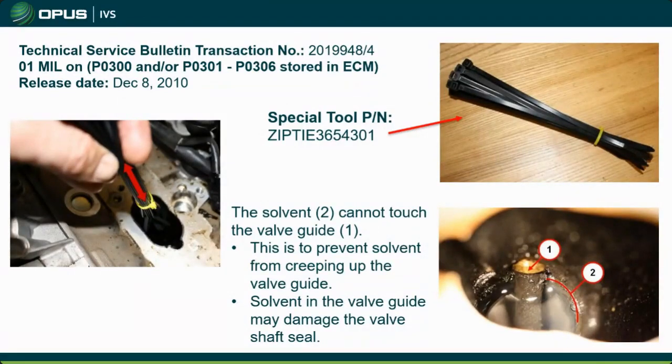The short trip driving is just a killer on these direct injection turbo and supercharged systems, because they never get up to operating temperature. The breather system never really gets cooking, in the sense that you're getting good separation, and you really just start burning up oil. And because we have these direct injection systems, we got nothing spraying on these valves to keep them nice and clean and shiny, and those deposits just build up and build up and build up, enough that they actually have technical bulletins about cleaning them.